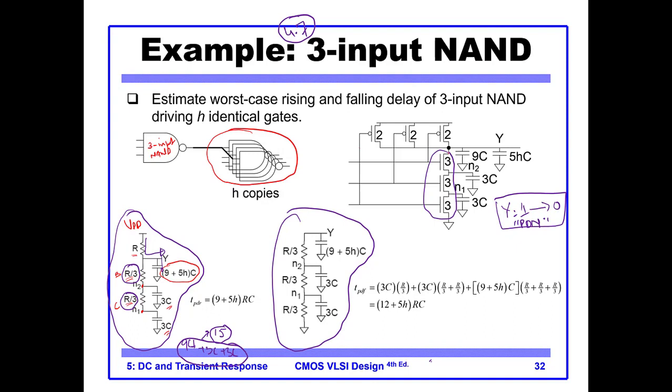You can say that it is the case when we have A is equal to 1, B is equal to 1, and C is equal to 1. For this combination, all the PMOS are off and the NMOS are on. So the equivalent circuit is something like this one.